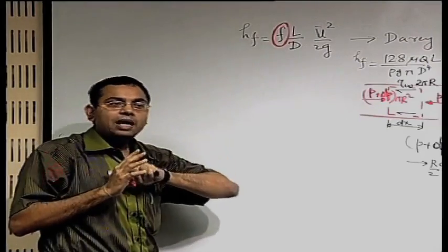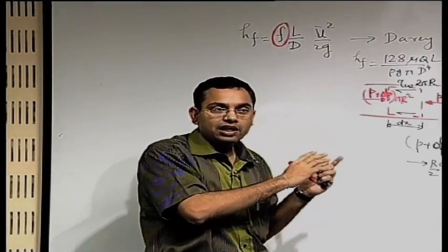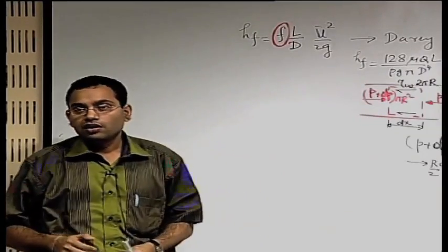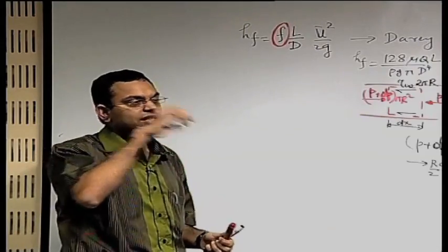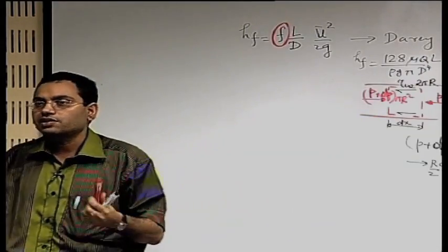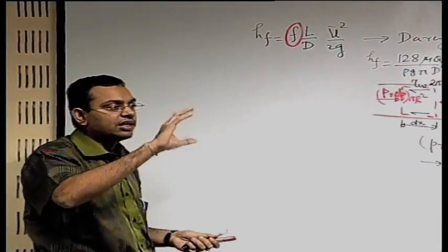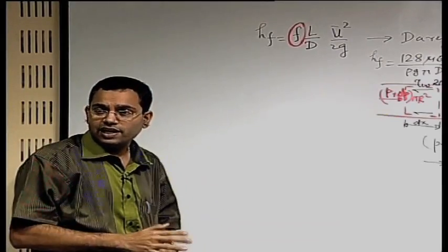For a fully developed laminar flow, we may determine it exactly by a very simple analysis which we have already done through the exact solution of the Navier-Stokes equation. As the flow becomes turbulent, such simple exact solutions are not possible, because you may only statistically operate on certain quantities and get an estimate of the velocity profiles with certain fitting parameters, but not something very exact.